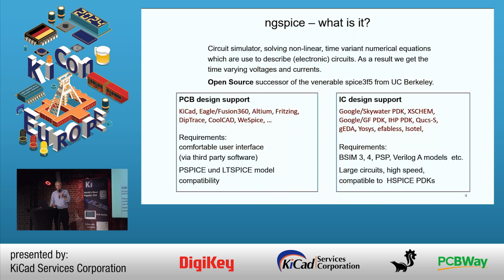And therefore we have ngspice. What is it? This is a circuit simulator. It solves the nonlinear time-variant numerical equations which are used to describe electronic circuits. And as a result of the simulation, we get the time-varying voltages and currents. ngspice is the open source successor of the venerable SPICE 3 from UC Berkeley. They started developing this and they made it open source very early. And so we are benefiting from them. And it's been more than 20 years now.